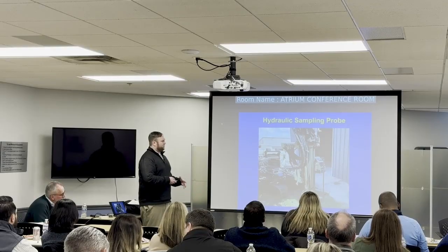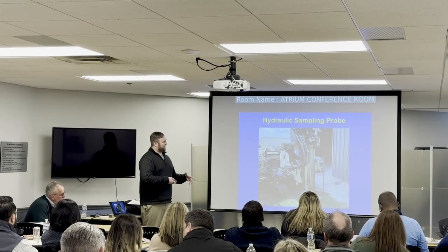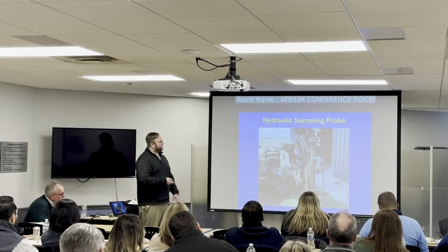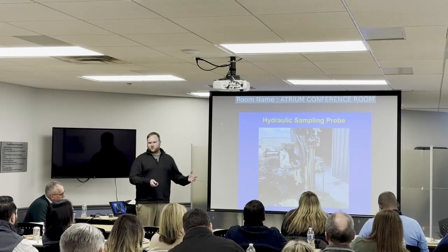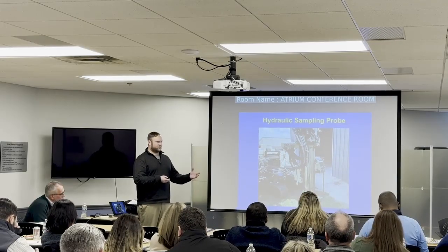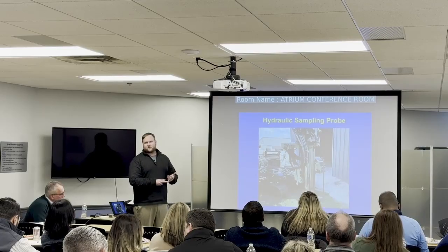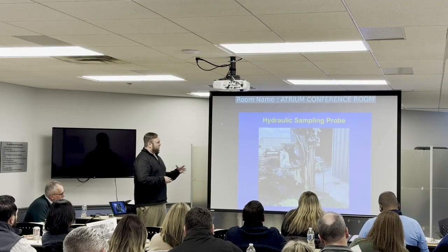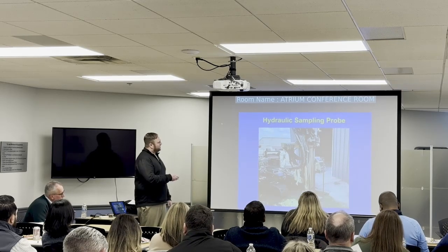It allows us to drill. You can take shallow borings from a few feet. We drilled down to 50 plus with these for environmental sampling, depending upon the area. You're collecting soil cores. Once those come up, the field geologist logs those, packages them up, field screens them, and submits them for analysis. This is a little more invasive than your air sampling, but a lot of times, depending upon the risk, this is generally what we go to first.